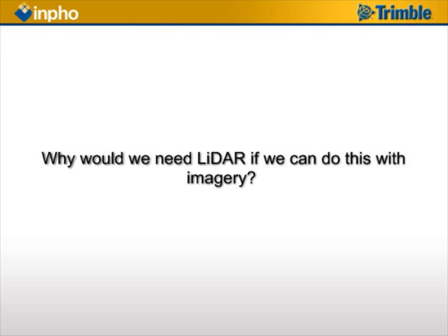So there might be applications where you still need a laser scanner, but in many cases, this automatic matching can really replace the laser scanner, or it can be a low-cost alternative. Just for an example, here in Germany, the state authorities are using image-based DSM extraction to update their LiDAR database.